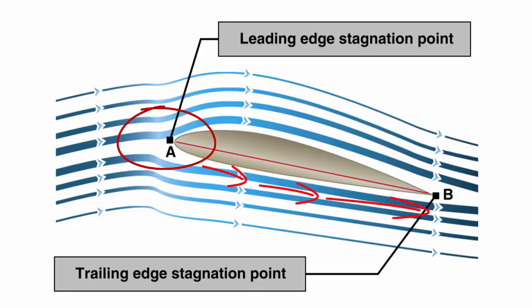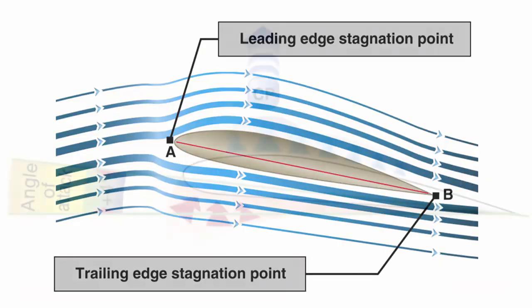At some point near the trailing edge, the airflow again reaches a velocity equal to the flow on the upper surface. Again, applying Bernoulli's principle, where the airflow was slowed beneath the wing, a pressure was increased and positive upward pressure was created. Both Bernoulli's principle and Newton's laws are in operation whenever lift is being generated by an airfoil.